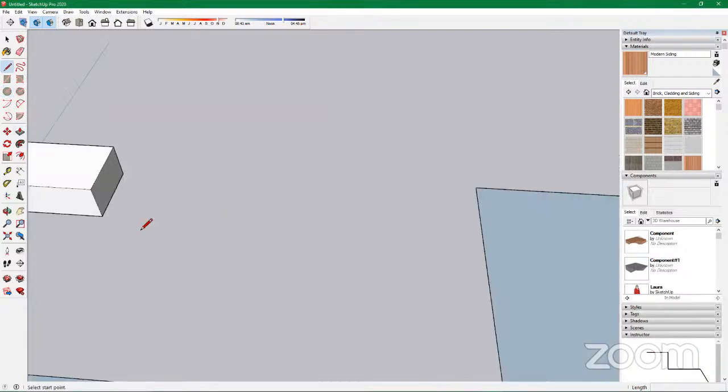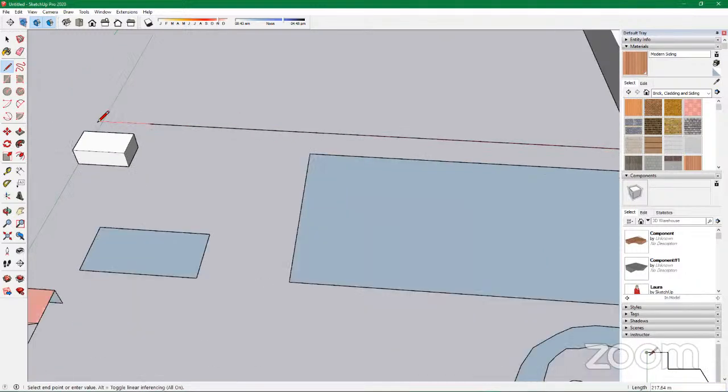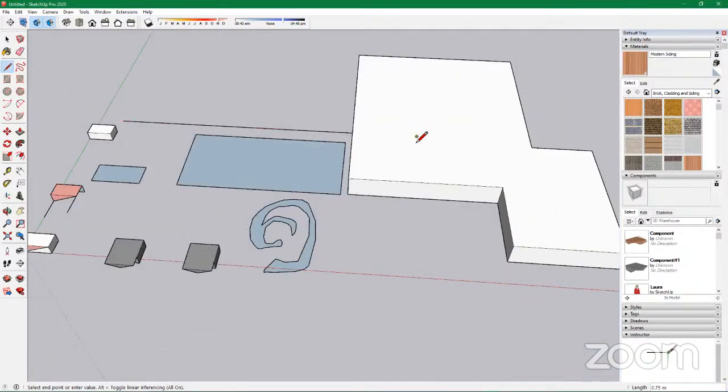So with the line, it will actually tell you the length of the line. So if I click my first point and drag, you see the line increasing. Just look at the lower right corner. You see the line increases and it decreases with respect to how long or short the line is. So I can impute the distance there, and I say I want it to be 1,000. Sorry, I don't want 1,500 meters. So I want 200 meters. 200 meters, and I okay. Giving you 200 meters, you see it went far even inside this.